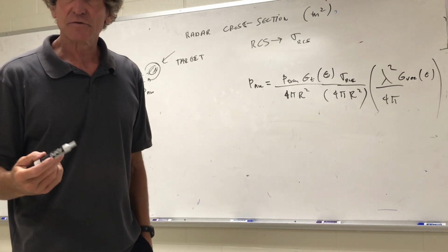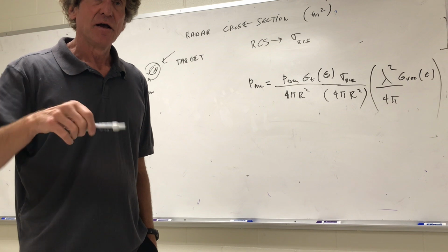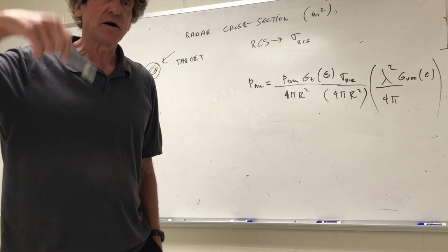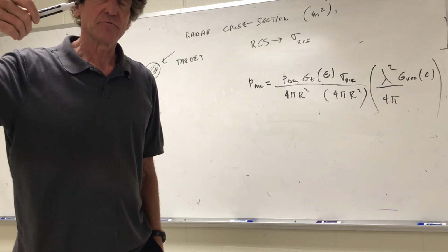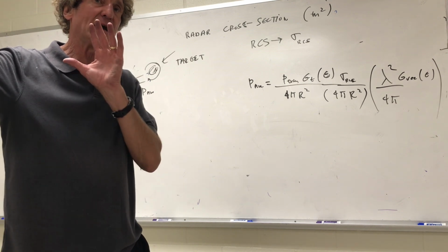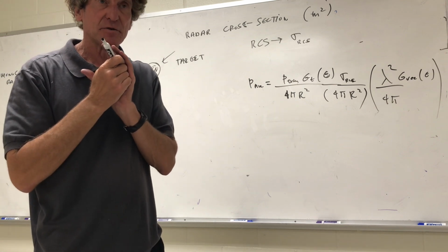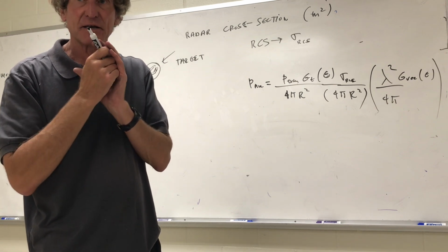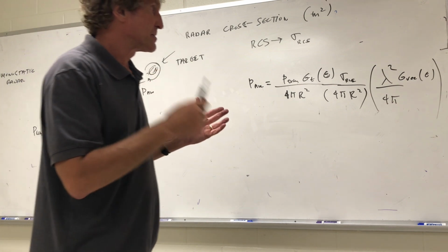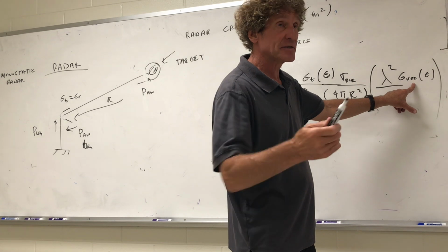And the whole idea is with an antenna, the exact same pattern of transmission, the angular function that would weight the power transmitted, the gain, is the same exact thing you weight the actual ability to receive information. It's a reciprocity kind of problem. So this gain here is the gain of the receiving antenna, as if it was transmitting.